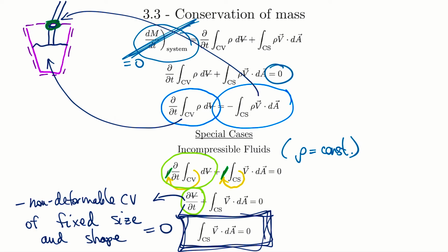So when I say I'm integrating the velocity over the area, over the control surface here, I'm integrating this term over this area here, which is our control surface. The only times you have to integrate that is if the velocity is changing over the area. So let me just draw the end of a pipe here. What would happen in most cases is the velocity profile would look something like this. We've seen one of these before. We'll get into more detail in later sections, but essentially it's slowest near the wall and fastest near the middle, which is true for laminar flows mostly.